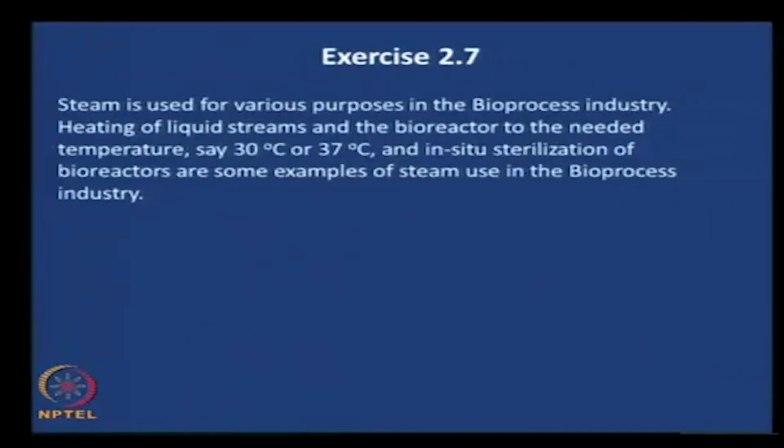There would be competition for the food that is available, which may not be desirable for the optimal production of the product, and therefore we sterilize things, we make sure that we have a clean slate when we start out, and under sterile conditions we add the microorganism of interest into the bioreactor and then let that organism grow and produce the product of interest. For sterilization, steam is used, slightly higher pressure steam and at temperatures of about 120 degrees, 121 degrees are used.